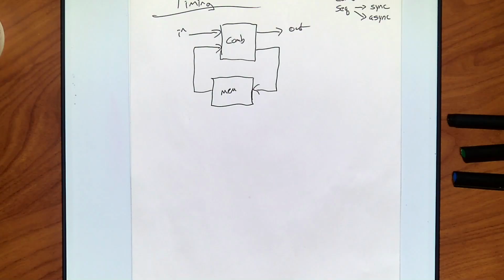What's RS? We just did it, right? Set and reset. The next easiest one, and we did use these briefly, what's a D? The data you want to store. You put the data on the input, and it's as simple as putting an inverter between R and S, so that in essence you force it to whatever you put in as the value to store.